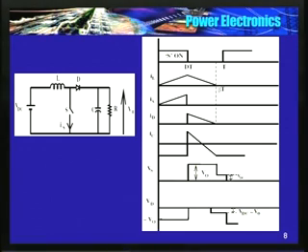No current flowing here, it is an open circuit. No current flowing here also. So potential at this point is equal to potential at this point. That is nothing but the voltage across S. So it drops to VDC. Maybe better for the switch, now voltage across it reduces. What happens to the diode?